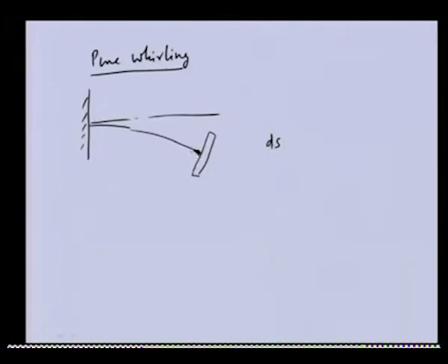This shaft segment, if we extend it, is nothing but a tangent to the shaft at the bearing location. So, we will see that this particular shaft segment will make a conical